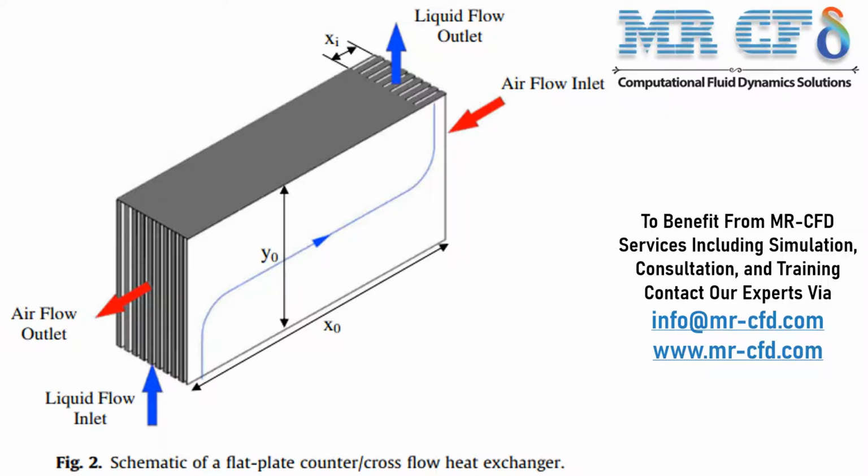In general, this panel belongs to one of the two panels in the closed cycle of solution and airflow. The fluids used in the present model include air and ethylene glycol, although their thermophysical properties are manually defined in Fluent. Ethylene glycol is a colorless, odorless, low volatility, low viscosity material whose properties are defined as temperature-dependent polynomials. Also, since hot and cold flows are not integrated in this heat exchanger, there is no need to use a multi-phase flow module, and on the other hand, a separating plate is used as an interface.